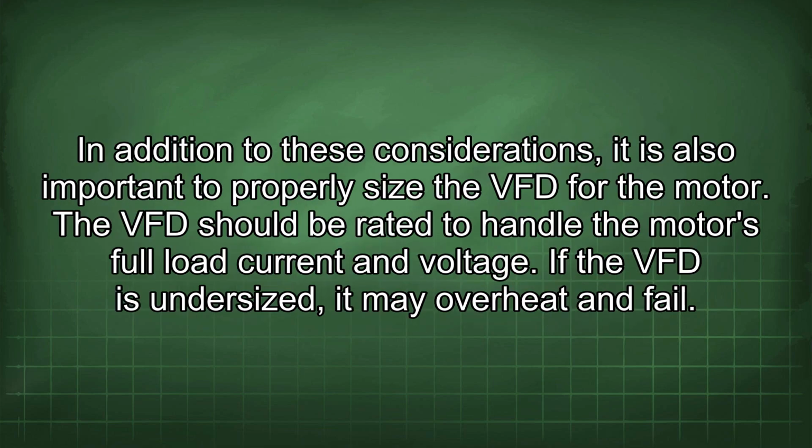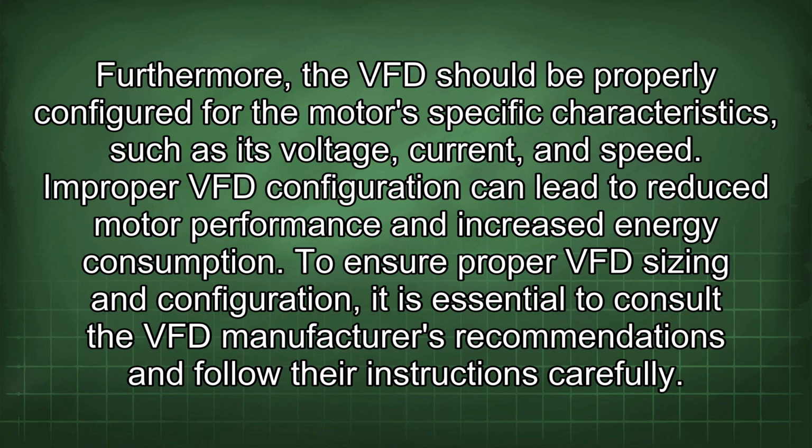In addition to these considerations, it is also important to properly size the VFD for the motor. The VFD should be rated to handle the motor's full load current and voltage. If the VFD is undersized, it may overheat and fail. Furthermore, the VFD should be properly configured for the motor's specific characteristics such as its voltage, current, and speed. Improper VFD configuration can lead to reduced motor performance and increased energy consumption. To ensure proper VFD sizing and configuration, it is essential to consult the VFD manufacturer's recommendations and follow their instructions carefully.